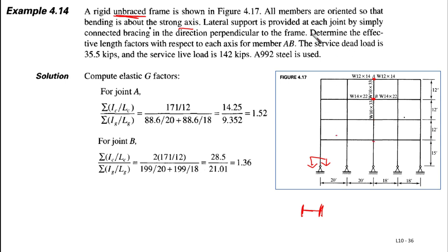Why is this needed to be given here? Because it is giving us a piece of information, telling us that the out of plane buckling length of the columns, which is normal to this screen, is going to be the same as the column length. So the effective length factor is going to be exactly 1. Out of plane means perpendicular to the white page. But in plane, the buckling length is going to be calculated, because it is a sway permitted frame.